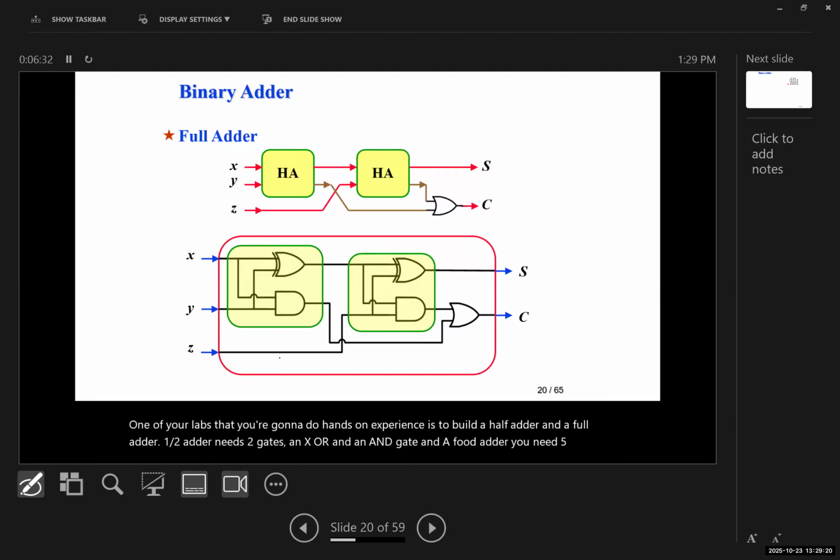Another type of combinational logic circuit is the magnitude comparator. This combinational logic circuit compares two numbers. We can have two 4-bit or 8-bit or 3-bit or 2-bit numbers, but usually the ICs come in two 4-bit digits. It's going to have three outputs: equal, greater, and less. So A could be smaller than B, A is equal to B, or A is greater than B.